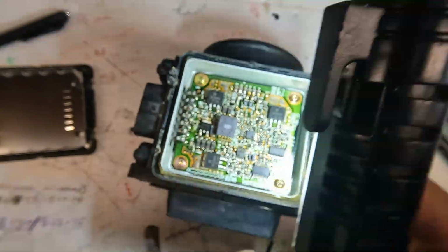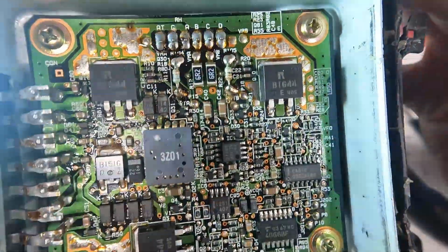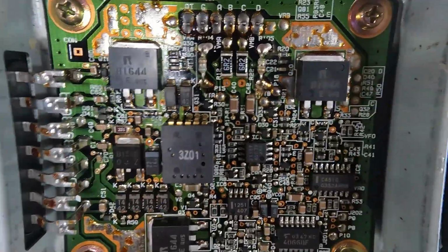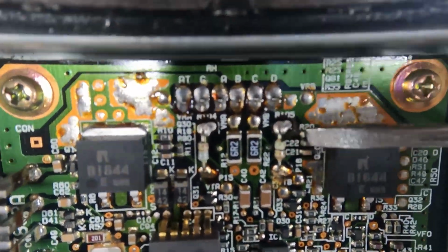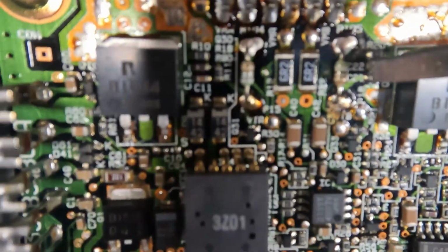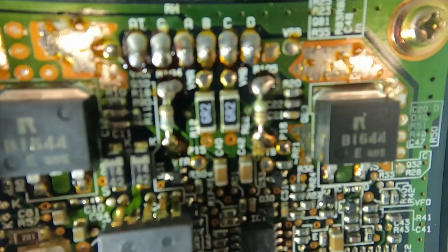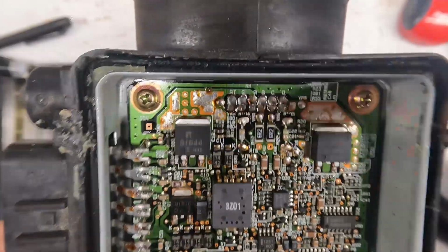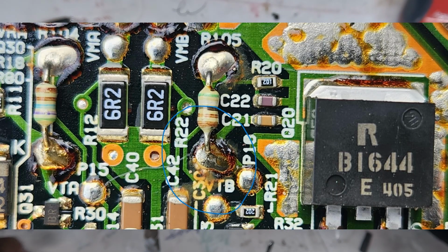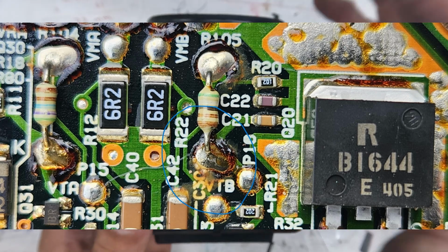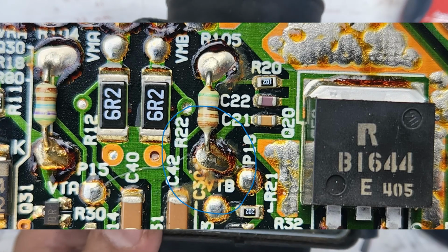Alright guys, look, I found where the issue was. I don't know if you could tell, but you see this resistor right here, that resistor is burnt. There's like a little burnt spot right there. I don't know how well this GoPro is focusing. So I'll put a close-up picture here. You can see it better on that area where that resistor seems to have gotten a little hot.